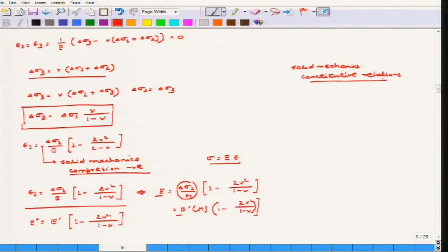So, this is just a demonstrative problem of how people generally model soil mechanics from an experimental to a computer program. This is how they use the definitions of stress, strain, Young's modulus, and all those things to predict the behavior of soils at different stress levels and confinements. This is only considering the linearly elastic range. Similarly, you can consider the plastic range, and you can go for the plastic behaviors of soil, but this is an entirely different domain. This is only to demonstrate how the shear strength relations of soils can also be used for modeling behaviors.